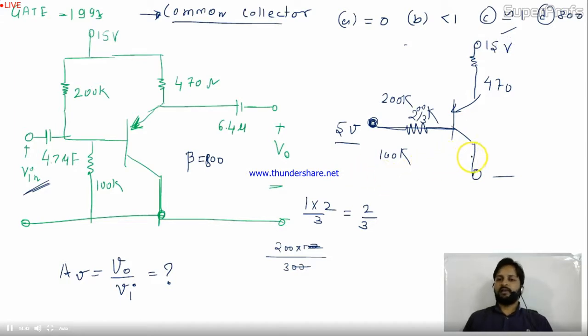Now you need to calculate IC. Why IC? Because you have to replace this by the equivalent circuit. In that I need IC DC, because I need to calculate beta RE there. Why are we doing this DC analysis? By doing this DC analysis, we can convert to the equivalent circuit of the transistor or BJT, right? We have seen just now that in the equivalent circuit of the BJT, we need beta RE, that is R pi. Beta is available with us. RE we calculate as VT by ICDC. I need ICDC, meaning the collector current IC in DC operation, right?